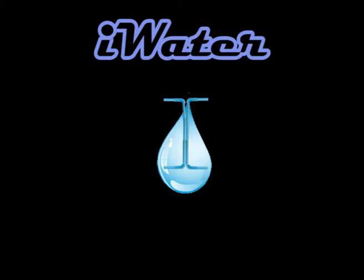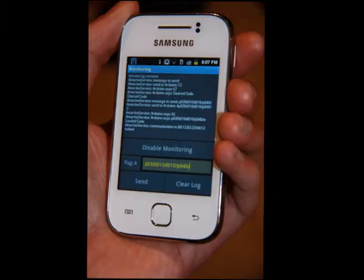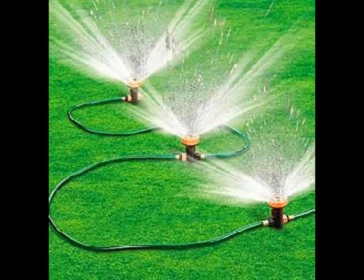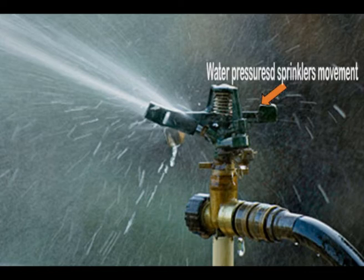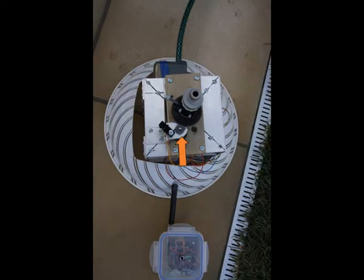My design brief for iWater was to create an irrigator that would be programmed to water a user-defined area at a user-defined rate. The standard water sprinkler is operated by water pressure. In more sophisticated versions, water pressure turns the head. In order to be able to control the sprinkler head's rotation, I had to use a motor as opposed to water pressure to power the rotation.